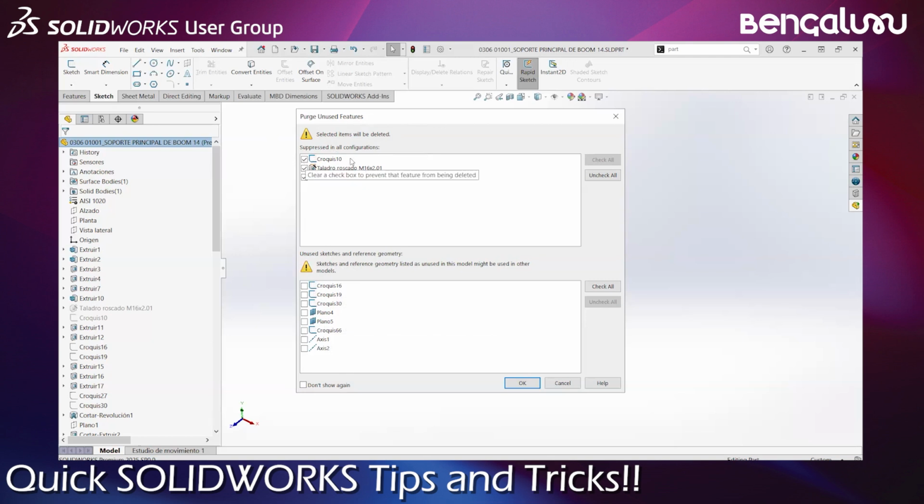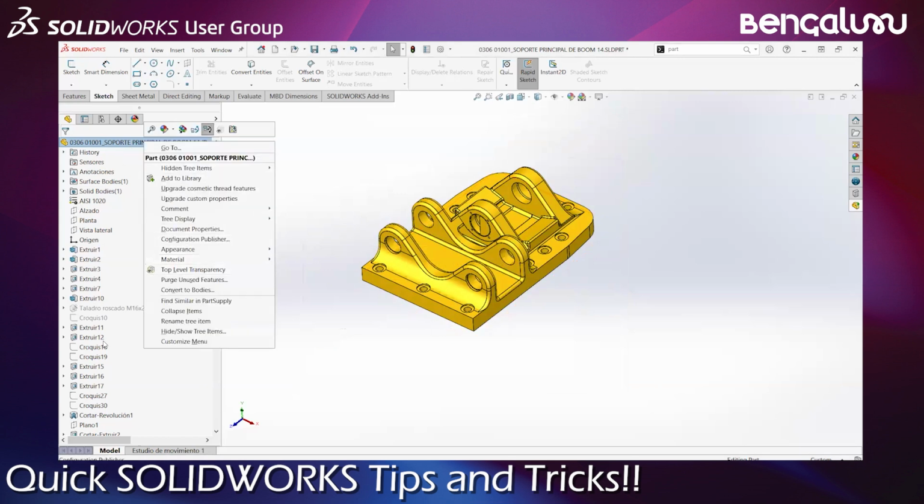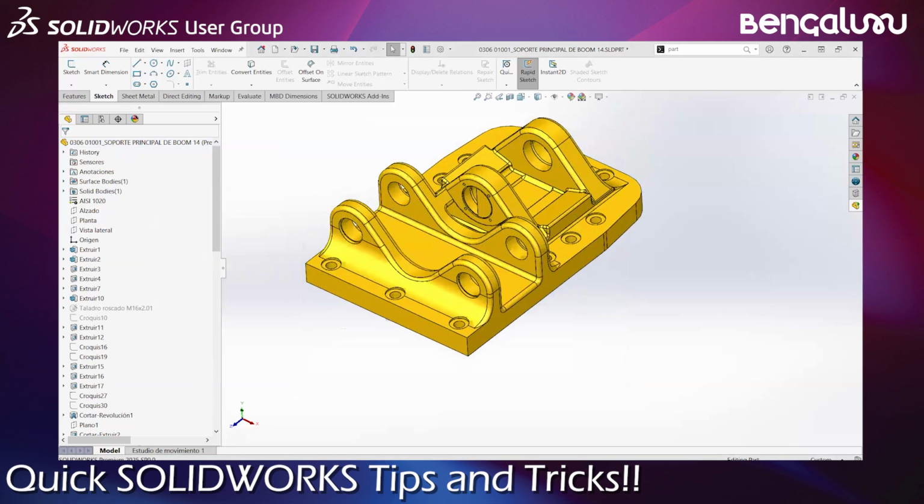So you can quickly review them, you can check them all or uncheck them all, or you can review all of these. And once you say okay, all of these things will be deleted from the model, thereby reducing the size of the part, ultimately improving performance, right? And this is not just on a part level, this is applicable for, or even on an assembly level, right? So it actually helps you save a lot of space by deleting the unused features. And that's a really quick way of finding them rather than having to search which of the features have not been used, right?